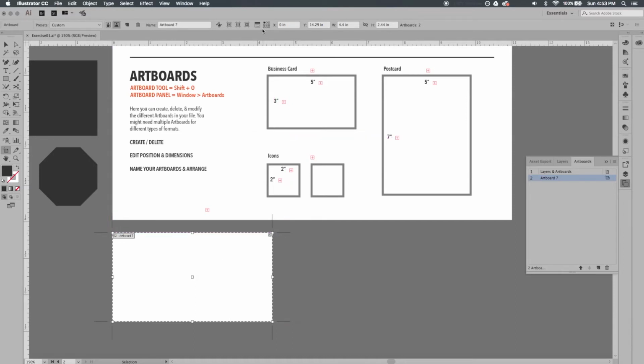So that can be found right up here in the control panel. You have a coordinates box here. With all of your objects, they usually have a coordinate system that they can grow or shrink from or multiply from. So right now, usually by default, the reference point is set in the center. So I'm going to make sure that my reference point is up here on the upper left. It's a little hard to see. You've got to get in a little closer to make sure that you have selected that upper left box. So I went ahead and clicked on that, and now I can come over here and input the values through my keyboard.